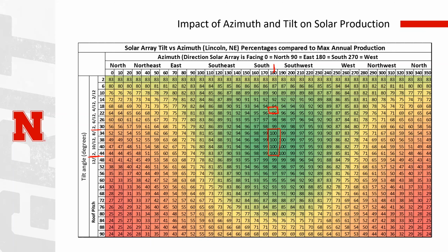Now, if you say, well, I only have an east facing roof, and it's 4/12 pitch, I'm losing right at about 20%. Actually, it's right here. But anyway, that's a 20% loss for an east facing roof. Now, is that a deal breaker? Maybe, maybe not, but I need to calculate that my production is going to be 20% less than what it was if it was optimal, and see, is it making enough electricity to justify the expense? The same way when I face it west, I'm losing right at about 20%.